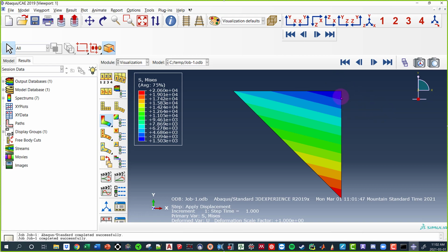So for instance, this node right here, node 3. Node 3 has DOFs 5 and 6. So if I were to probe the horizontal displacement at node 3, I can get my stiffness entries 5-1 and 6-1. Does that make sense? 5-1 is going to be the horizontal reaction at node 3, and 6-1 is going to be the vertical reaction at node 3. Does that make sense to you guys?